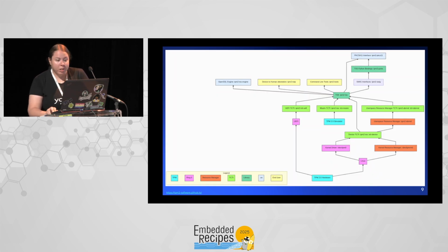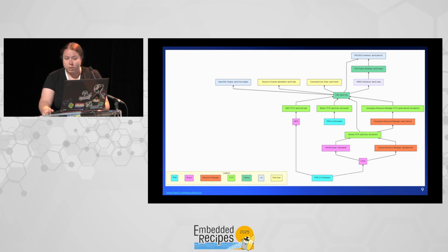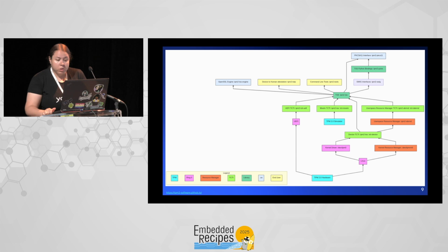And I brought a really wild picture from the TPM2 software GitHub page, the GitHub organization also implementing the TPM2 TSS software stack. It's a bit wild. I don't know if you really see it from your perspective right now, but what I like about this picture is that it clearly shows the HAL functionality of the TCTI implementations. There's a UEFI implementation, for example, a simulator implementation, and several for the device in Linux. It also makes clear that there are 2 TPM driver implementations and devices available in Linux, one with a resource manager available and one without.